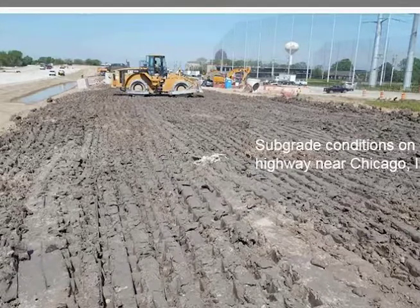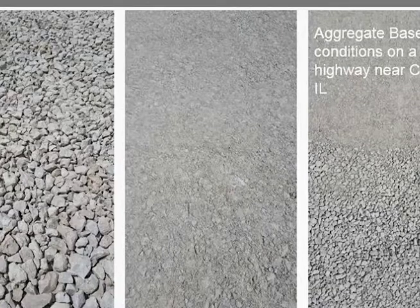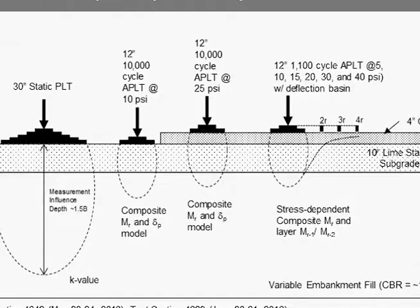What they needed to do is just reduce the moisture content. It was as simple as that. Aggregate materials vary in gradation. They become segregated. The stiffness varies. We saw a lot of variability with that as well. And so we came up with a test program that varied the size of the plate.